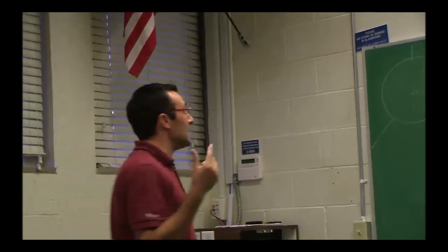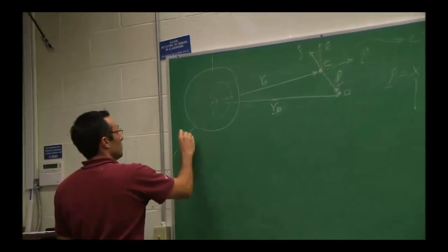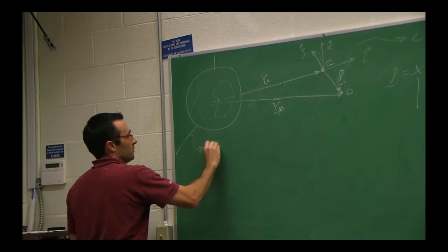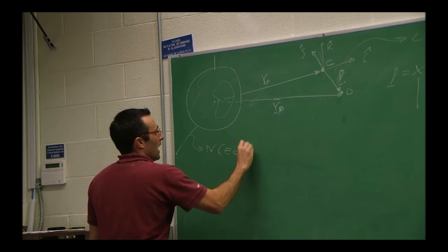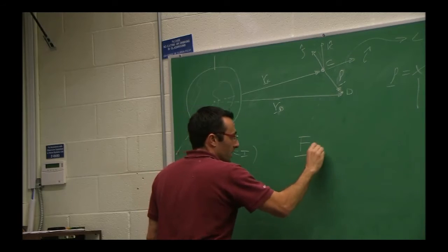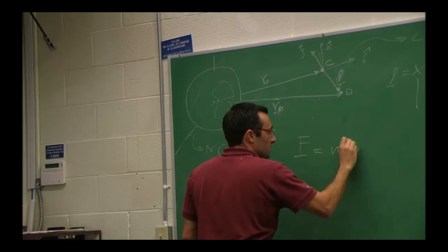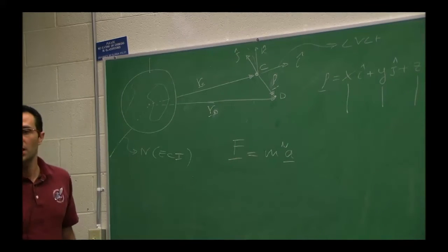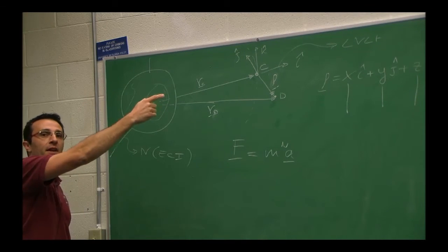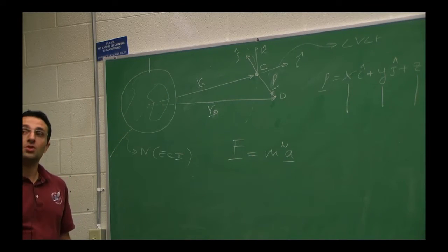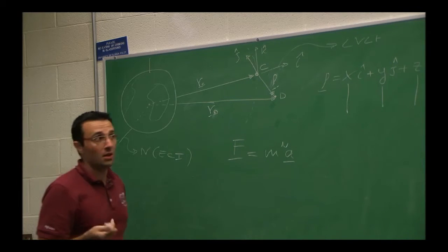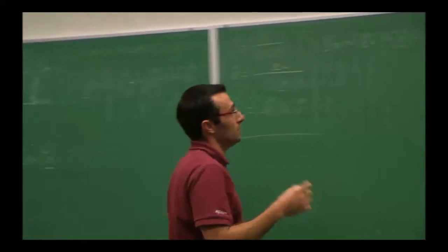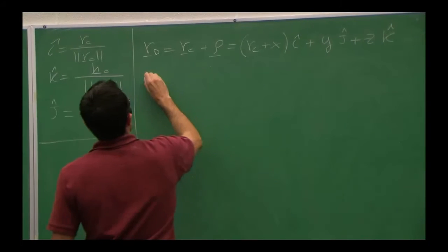You have to do it in an inertial basis, which, let's call this n, which is actually ECI, right? Why? Because F equals ma is only valid if a is computed by an inertial observer. So I'm going to take the rate of change of that vector twice, which requires the transport theorem because it's not expressed in a basis that is inertial. Okay, so no big deal.